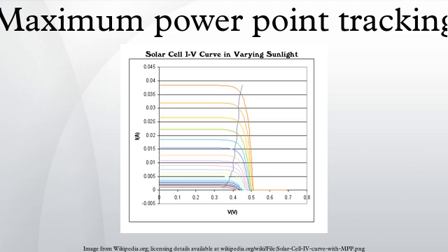In the constant voltage ratio method, the current from the photovoltaic array must be set to zero momentarily to measure the open circuit voltage and then afterwards set to a predetermined percentage of the measured voltage, usually around 76%. Energy may be wasted during the time the current is set to zero. The approximation of 76% as the MPP-VOC ratio is not necessarily accurate though. Although simple and low cost to implement, the interruptions reduce array efficiency and do not ensure finding the actual maximum power point. However, efficiencies of some systems may reach above 95%.